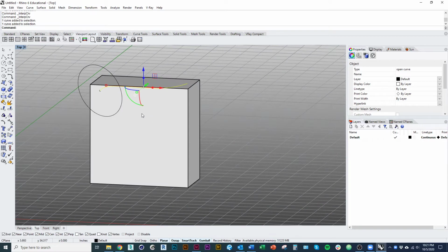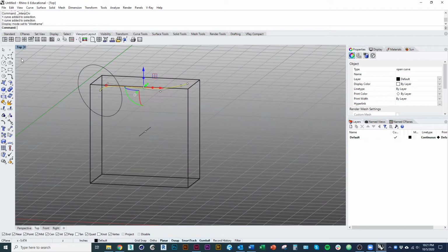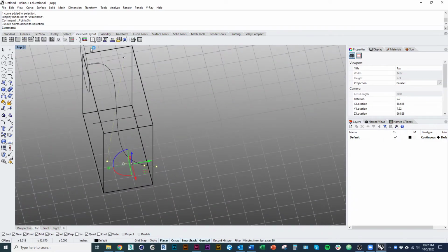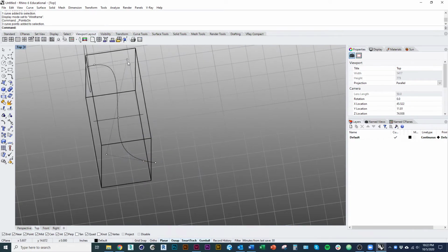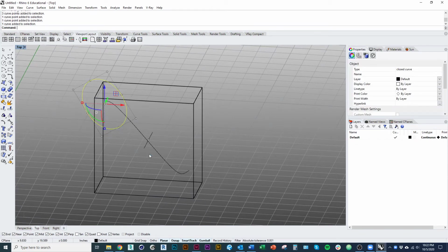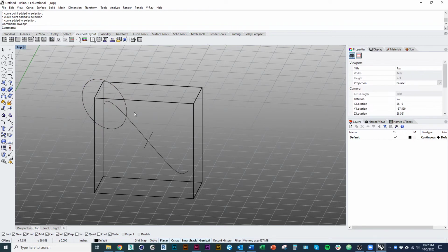And if I go to wireframe again, I could start to turn the control points on for this guy. I'm going to manipulate this curve just a little bit so it kind of weaves through my surface. Simplify just, there we go. Okay, now I'm going to use a command called sweep 1. So I'll type in sweep 1. Actually, make sure I have nothing selected first, because it's important the order in which we select our outlines for this.